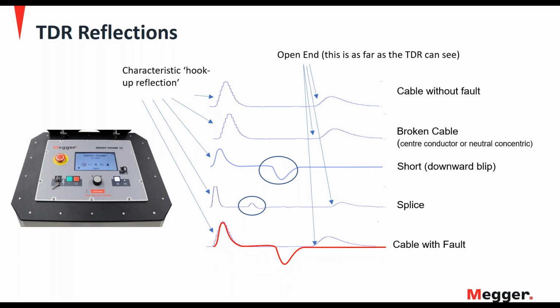And then finally, back down to the bottom, the cable with a fault. This is where we use the thumper to create an arc. The radar reflected off the arc. We display it in red to indicate it's a high voltage reflection. And of course, the fault distance is right here where the separation point is.